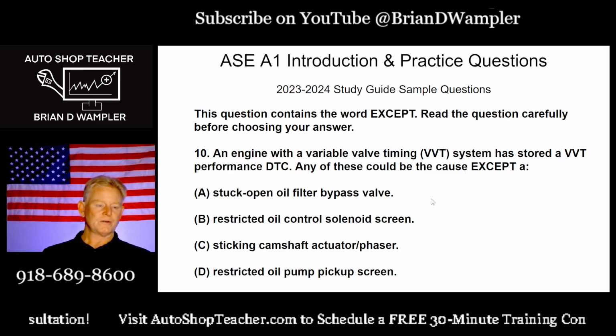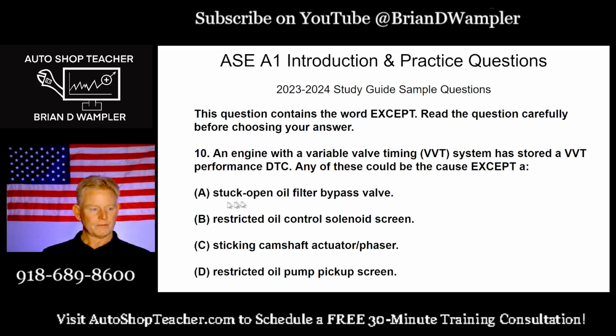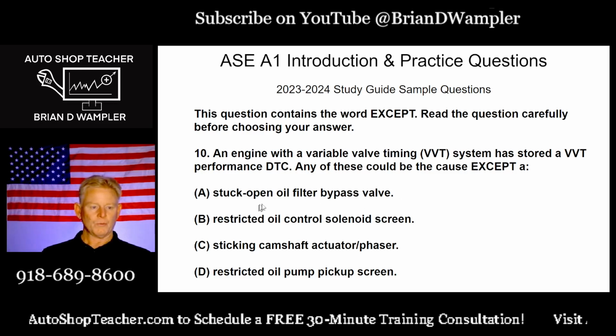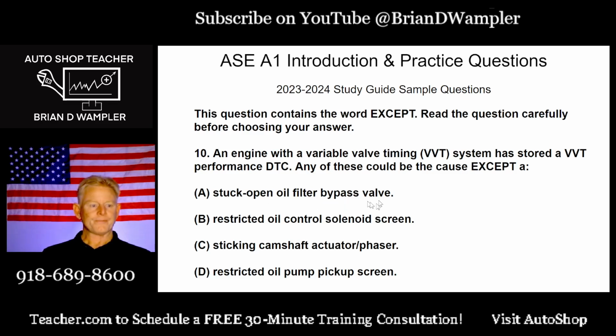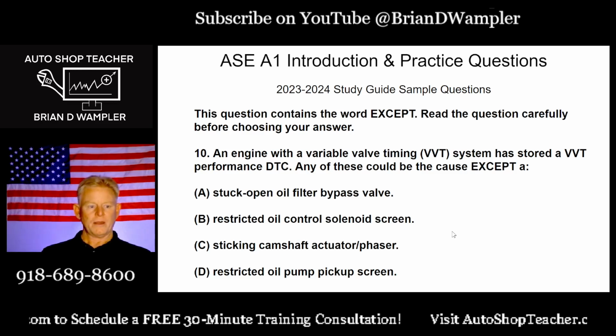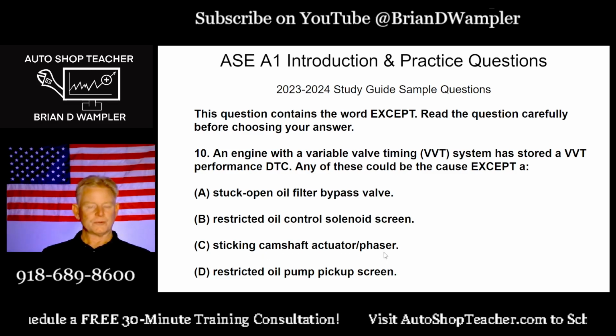Our 4 choices are a stuck open oil filter bypass valve. Make sure you always read the whole description. Okay? Which bypass valve? The oil filter bypass valve. Restricted oil control screen. Sticking camshaft actuator or phaser. Those are synonyms.